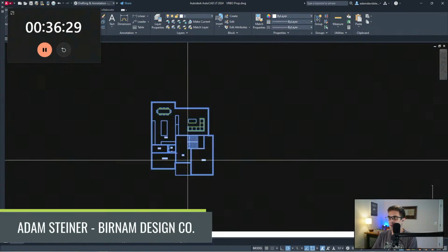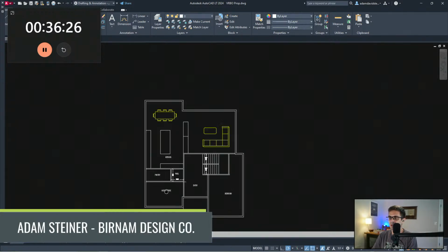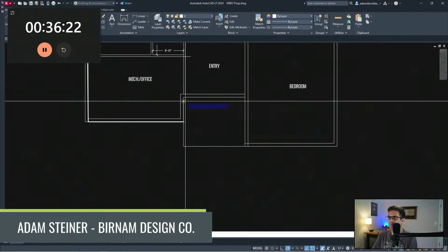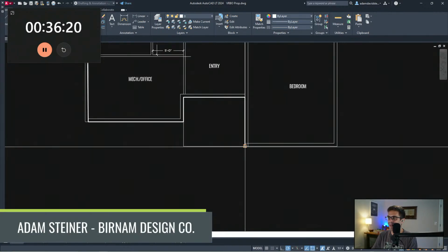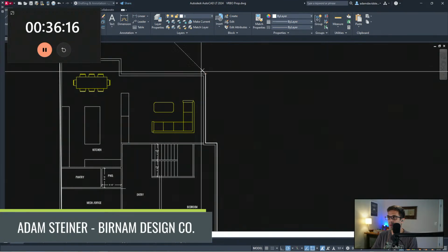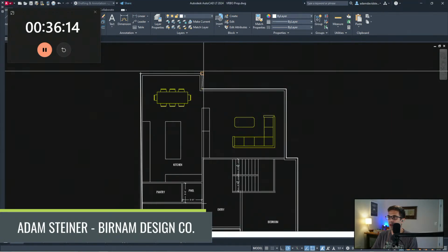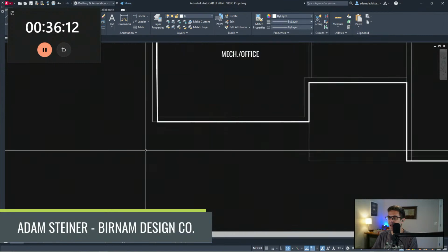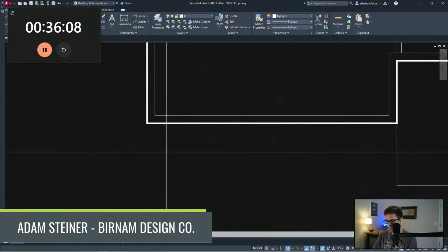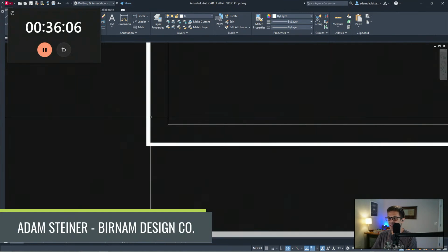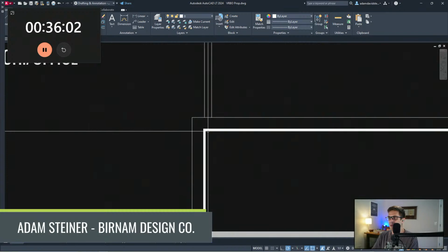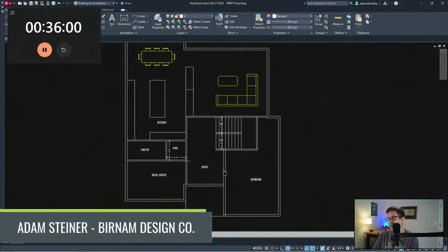Okay, let's jump up to the second floor. Oh, sorry. Before we do that, square footage. In AutoCAD, I'm just drawing a polyline as the perimeter of the home, which will give us our square footage. Outside of the walls, I include wall sheathing in that number. So usually showing a 6-inch wall, 5.5 for the studs, and roughly a 1/2 inch for sheathing. 1690 on the main, which isn't crazy for main floor master.